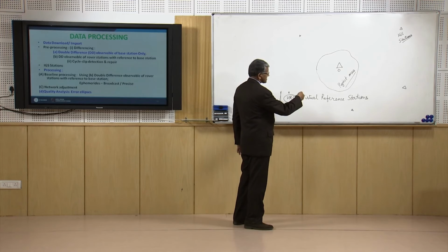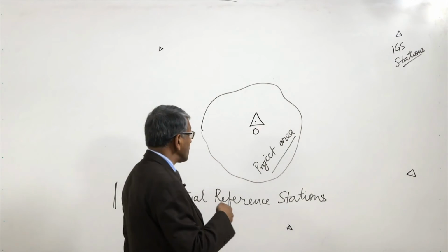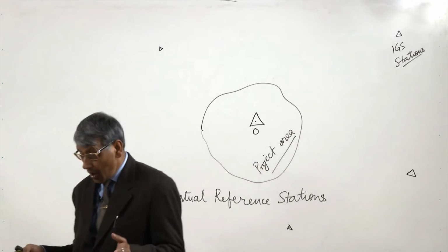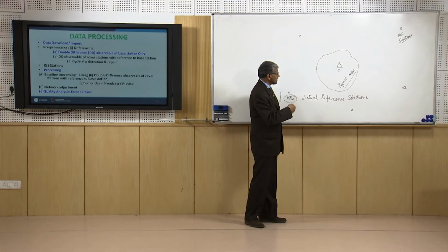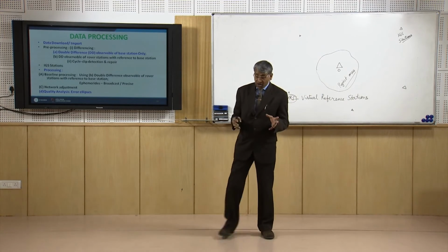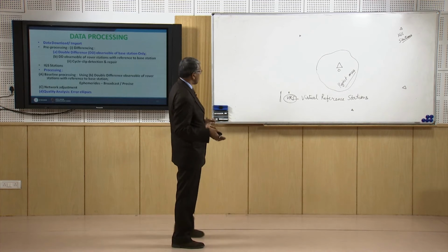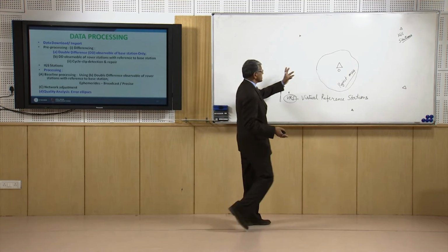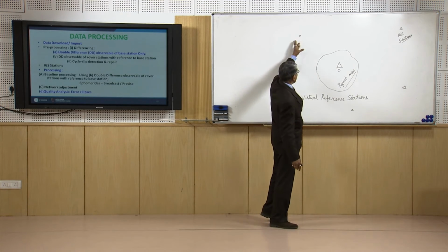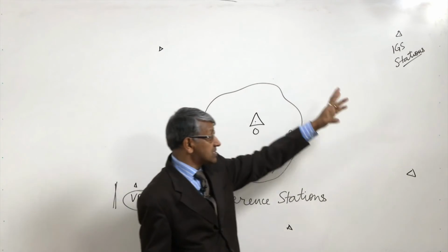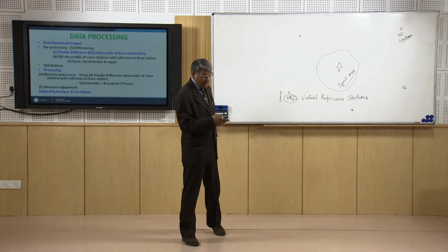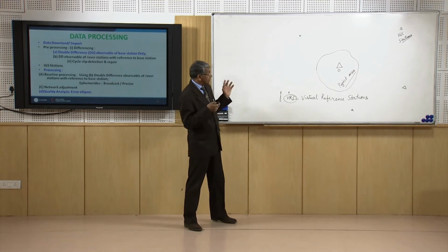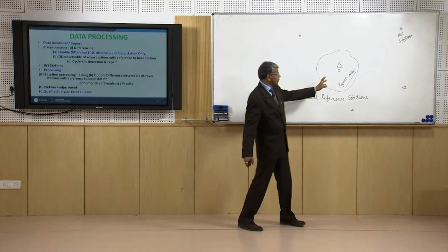So, this is the base station, and now we should see what is the duration, on which day, during which time we have the base station data, and during the same time we should search all over the world for IGS stations, on the same day. What are the IGS stations where data has been observed having the epoch same or less than what we have taken.